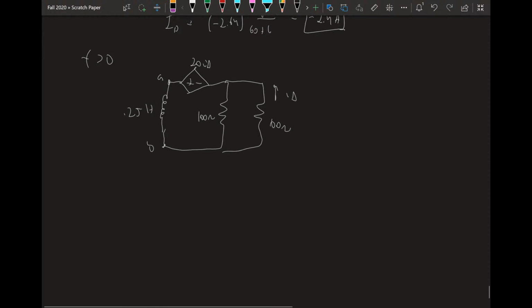All right, going back. So let's recall how we found the Thevenin resistance. And we only care about Thevenin resistance, right? We can already tell the Thevenin voltage here is going to be 0. There is no voltage. We call it an open circuit, voltage is 0. There's nothing going through the circuit. So let's find the Thevenin resistance.